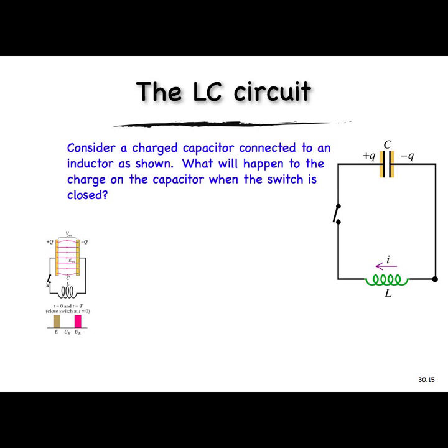You can generate very high voltages that way. That's actually the way high voltage pulse power supplies work. You can take something like a battery, just has 1.5 volts or something like that, but then have an inductor interrupt the circuit and get a very short but high voltage pulse coming out, and use that to power high voltage pulsed devices.